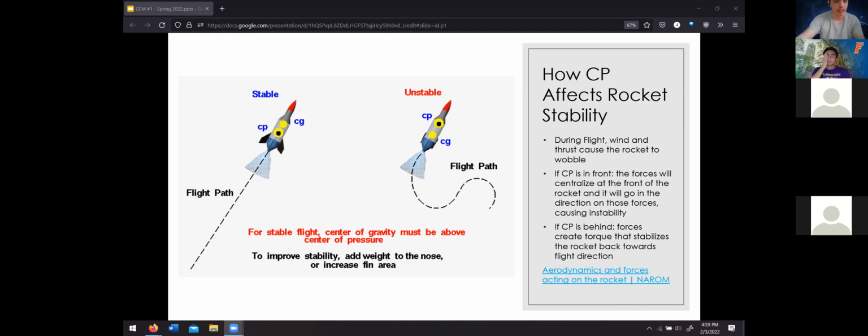And as you'll see later on, as long as you reach a certain amount of stability, you're super good. But another thing you can see with this example is that if you push on this body, your rocket will go into whatever direction of the wind if it's overstable. This is something we probably shouldn't be worrying about too much yet. But if you have your rocket too stable, your CG is too high, then your rocket will always coast into the winds very strongly. But for our purposes, it's much more important that the rocket is stable.